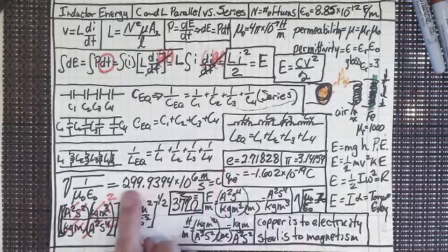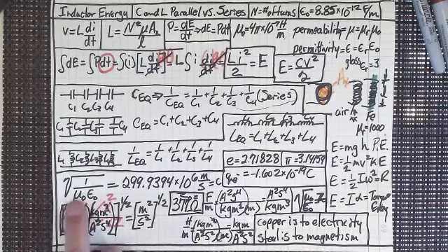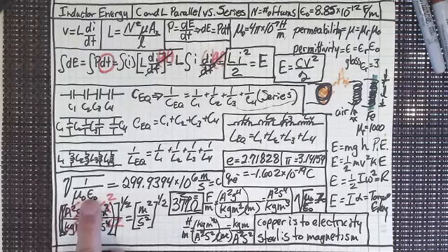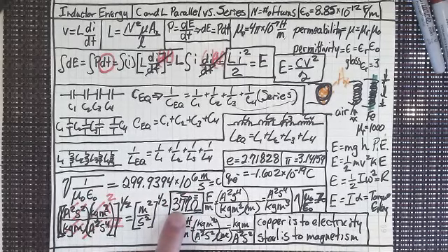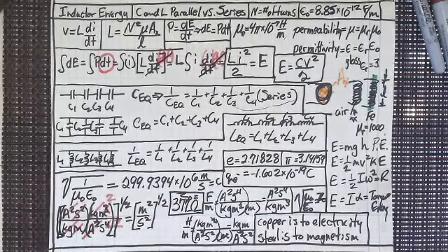So not only does this tell us what the speed of light is, it also tells us what the impedance of outer space is, right? And of course, the impedance of outer space is the impedance of the atmosphere too, because for air, mu sub r is very close to 1, and epsilon sub r is very, very close to 1. So when we're broadcasting microwaves through the atmosphere, we're broadcasting through an impedance of 377 ohms. That becomes more important later on when you'll be taking electromagnetic waves.